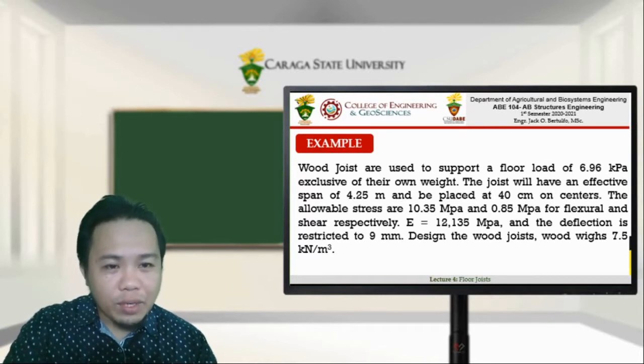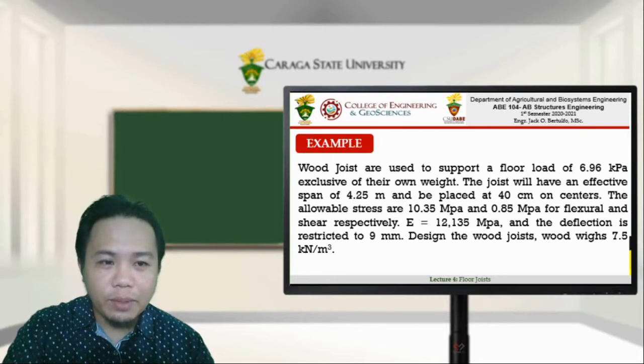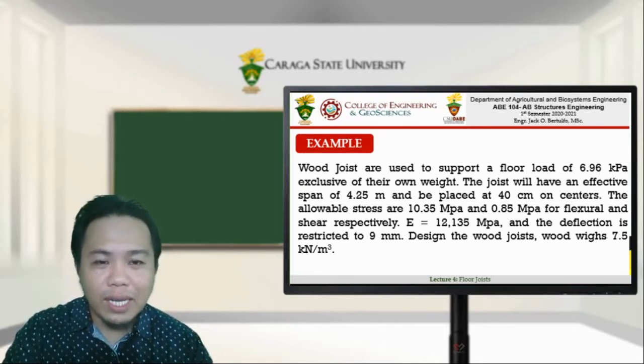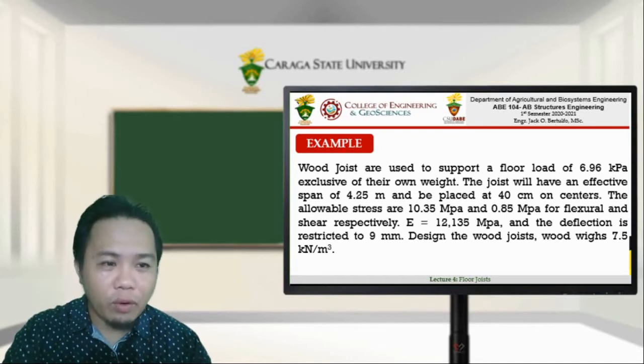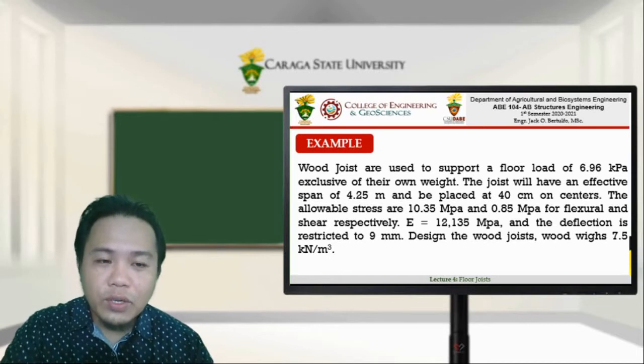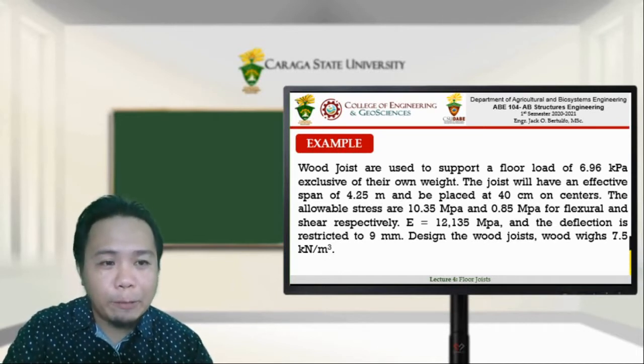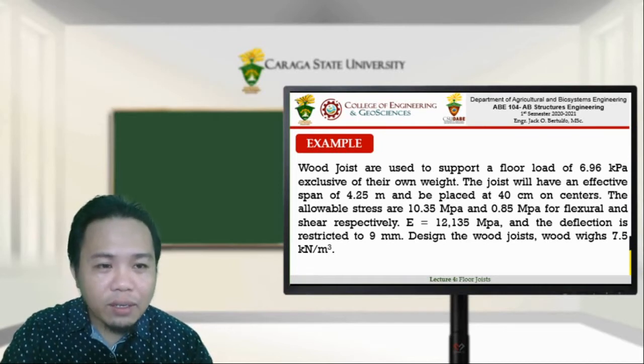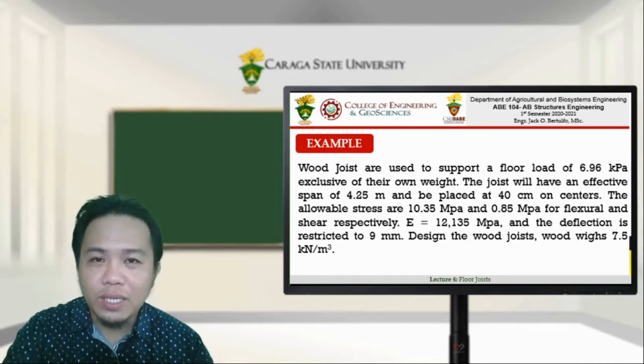The allowable stresses are 10.35 MPa and 0.95 MPa for flexural and shear stress, 10.35 for flexural or bending, and 0.85 for shear stress. We also have the modulus of elasticity, which is 12,135 MPa, and the allowable deflection, which is 9 mm.